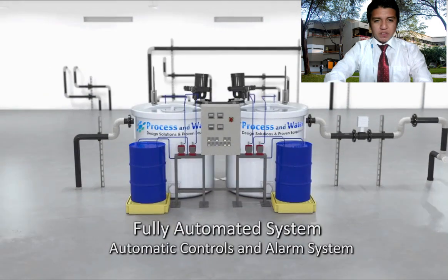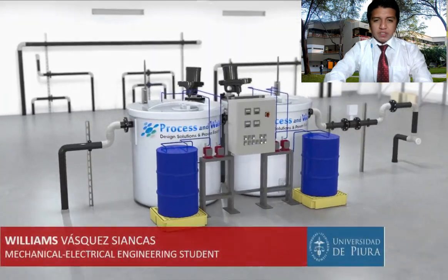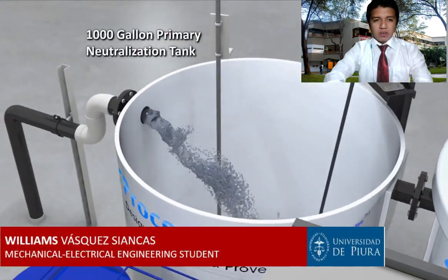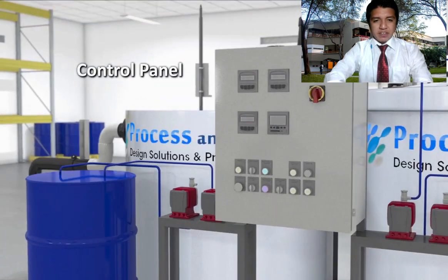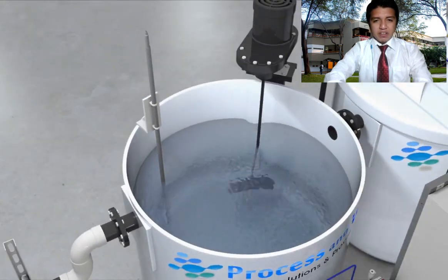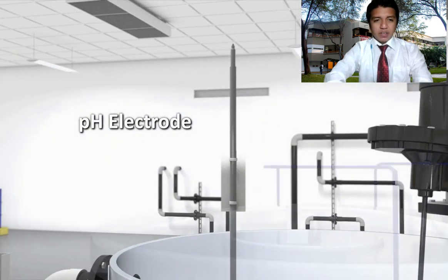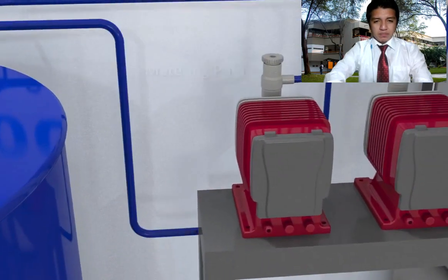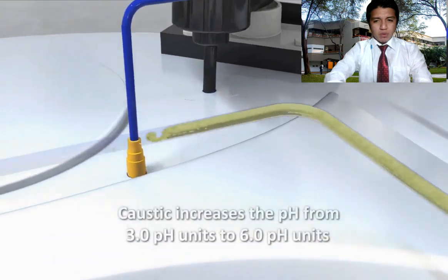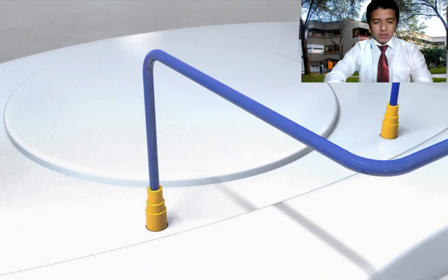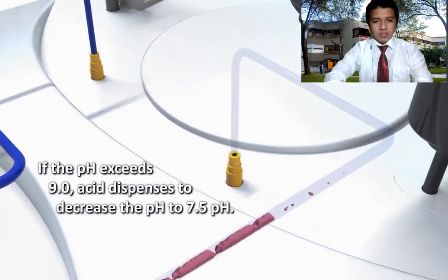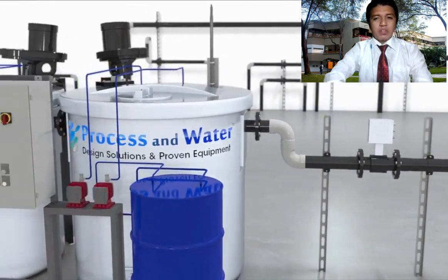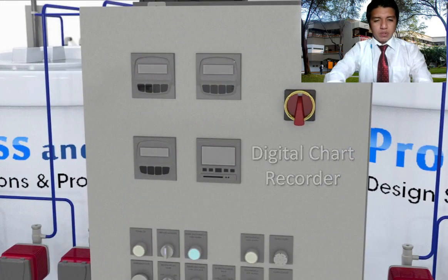pH neutralization processes are typical industry processes in relation to environmental or compliance requirements. Changes in pH can modify the concentration of other substances in the water, modify the level of toxicity. Decreasing can increase the amount of soluble mercury in the water, while increasing can cause the conversion of non-toxic ammonia into a form of toxic ammonia.